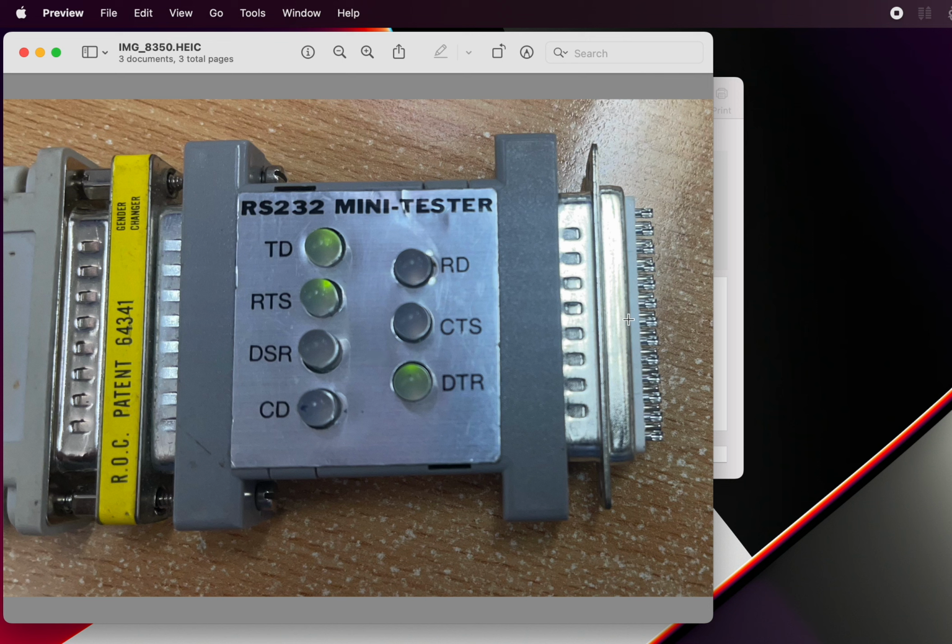So on this side, this is where you would have your PTT button connected, depending on whether you've got a 9-pin or a 25-pin. Anyway, just to help you with diagnostics, to make sure the electrical side is right, one of those little test modules is very handy. And this is what the lights should look like when you've got it plugged in to the 232 to USB converter.